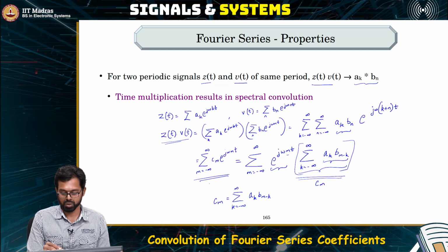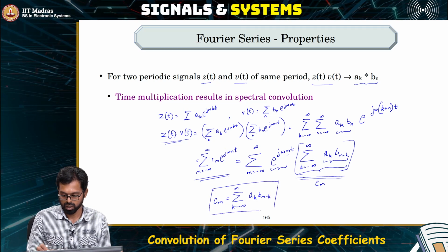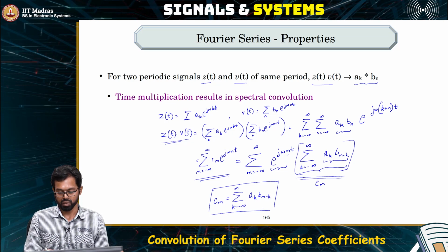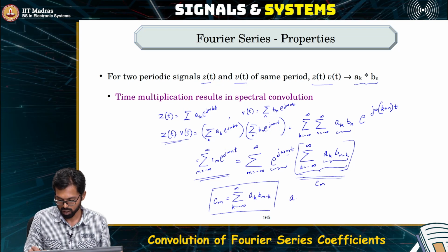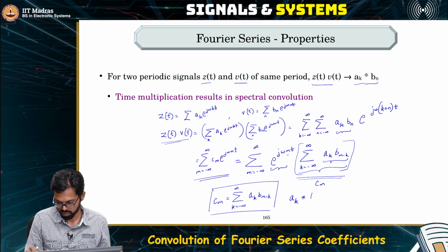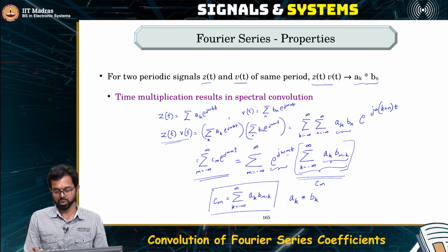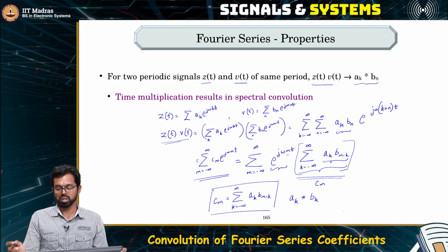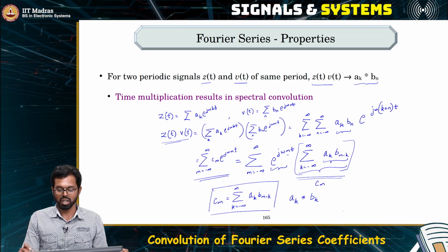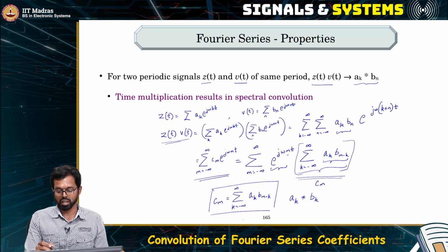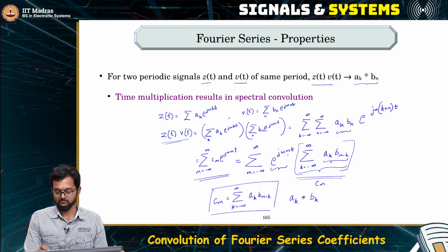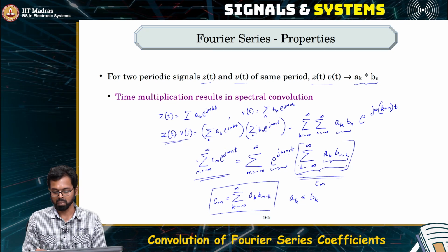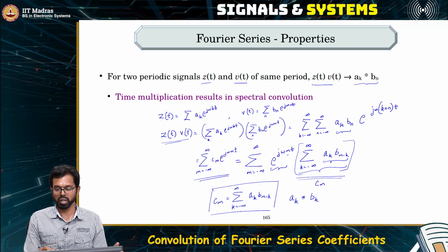So this is very similar to something that we have seen before, but in a discrete sequence, which is nothing but convolution of two discrete sequences. So we have two discrete sequences. We knew how to convolve continuous time domain signals. So what if, instead of being continuous, it was discrete? You just replace the integral with summation, and whatever was in brackets you just put in subscript and get rid of the dt term, or d tau term, and that's exactly what we have here.